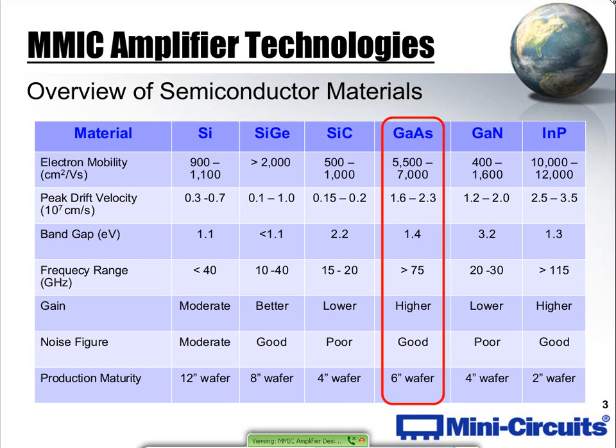So our opinion, or our position, is that we see gallium nitride is really going to take the lead, is taking the lead, and will take the lead in the future on the power front. There are some more esoteric materials such as indium phosphide and more exotic materials. They're used in more special applications like higher frequencies, the mid to high millimeter wave bands.